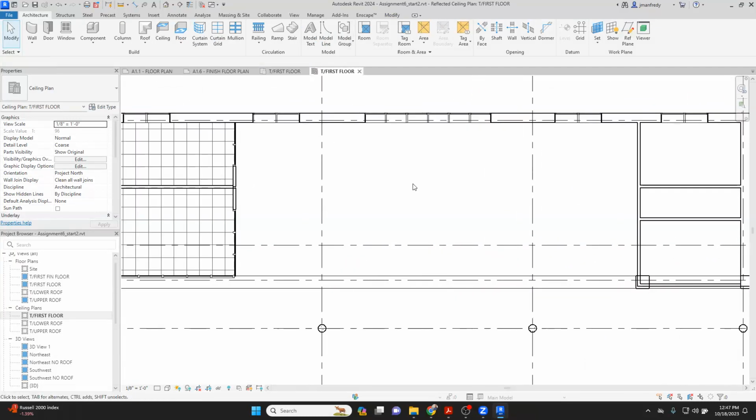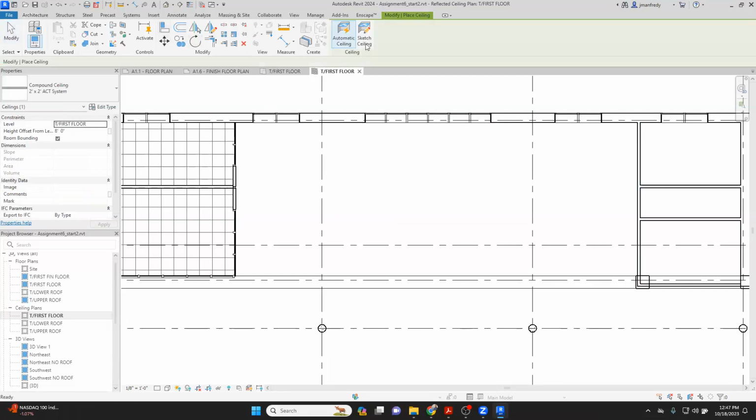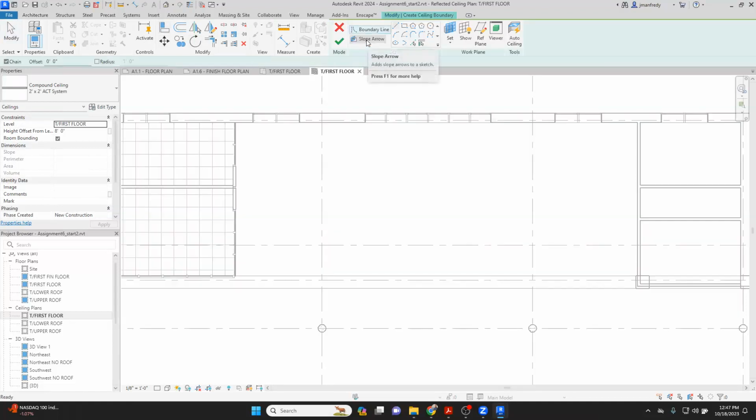So this area here is missing a wall because this is where the beam is, this is 11'4", and so the ceiling escaped. It grows until it finds walls, windows, and doors to contain it in an area, like the hatch pattern in AutoCAD. So if you've got that problem, you should resort to the other option: ceiling sketch, where you draw the ceiling.